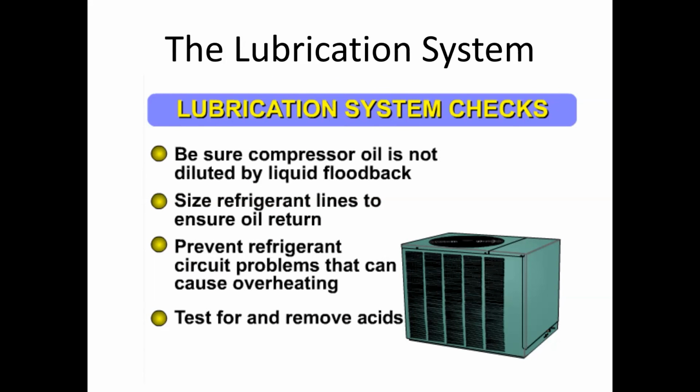So we want to make sure we're not flooding liquid back to our compressor. How do we do that? We make sure we have measured superheat at our indoor unit. When I talk about superheat as it refers to checking your charge, we don't really charge by superheat unless you've got a system that has a piston. Most of them have a TXV. But it is important to know what that superheat is.